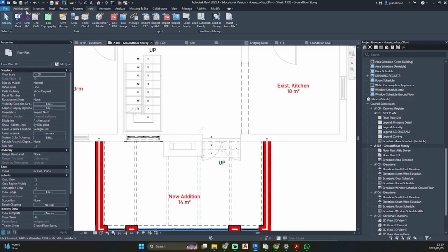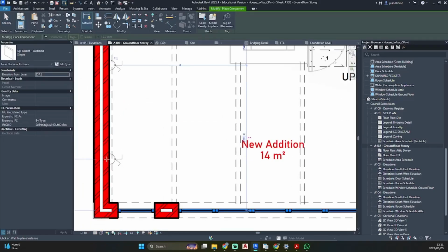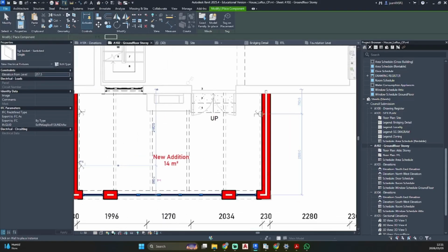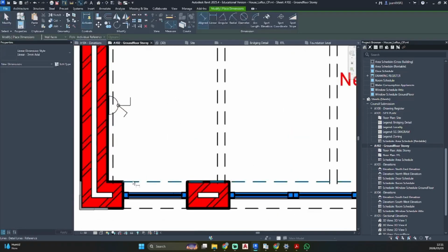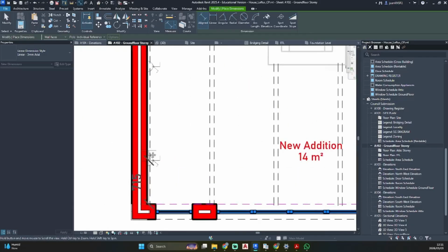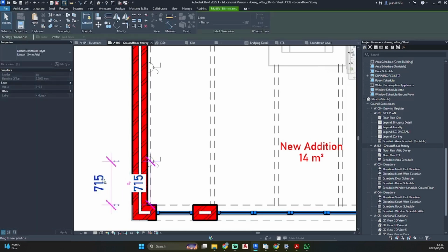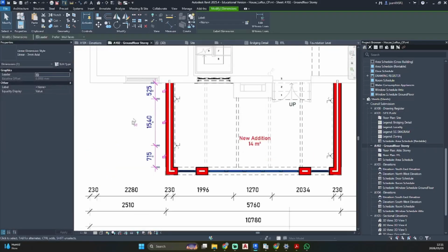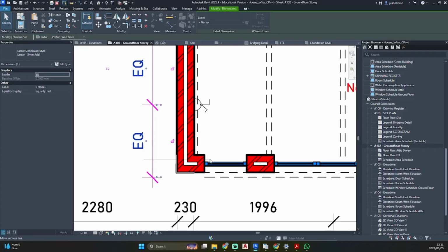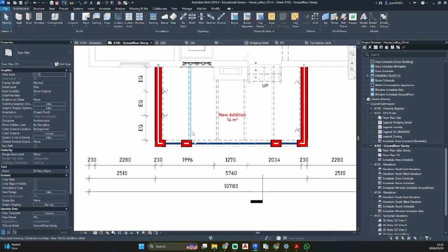And I'm going to go architecture component so that I can place my socket over there and one socket here and here. So now I just need to space them. I would like them to be equal. Smooth that out so we can select it easier like this, and let's just hit equal. And let's just maybe move this to the inside. There we go.